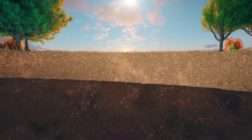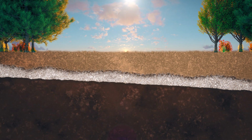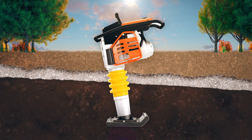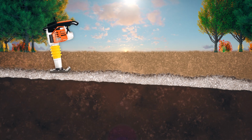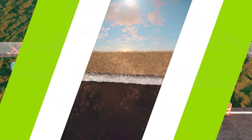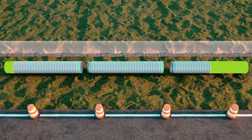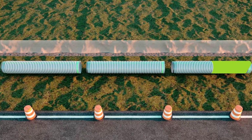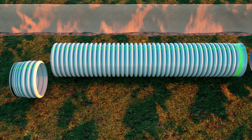Place and compact the specified bedding material in the bottom of the trench as bedding for the pipe. Compaction should be performed with appropriate compaction equipment, such as a jumping jack, to ensure proper bedding and trench support. Use appropriate backfill material per project specifications. Prior to placing the pipe in the trench, identify which ends of the pipe will connect to the precast safety end treatments. Once identified, cut the bell and/or spigot off.